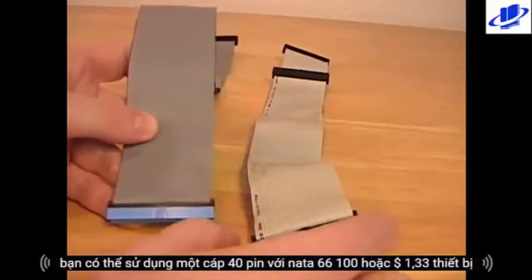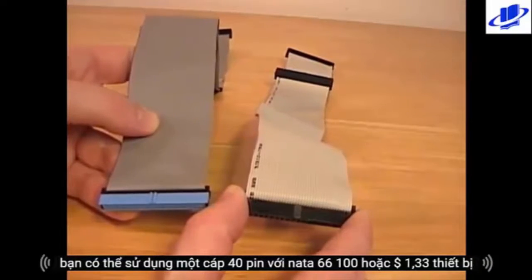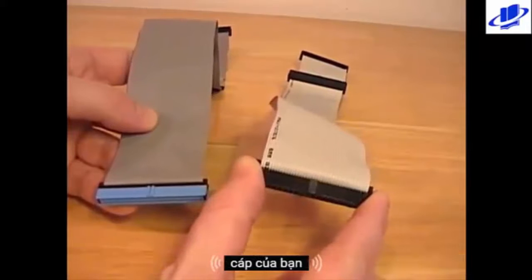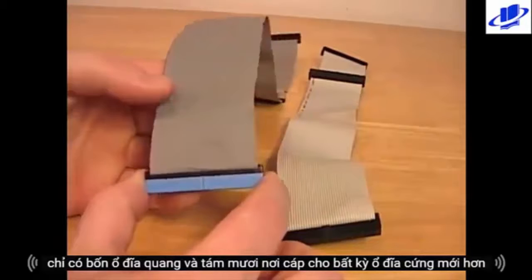You can use a 40-pin cable with an ATA 66, 100, or 133 device, but it won't run at the fastest speed. So it's recommended to use the 40-wire cables only for optical drives, and the 80-wire cable for any newer hard drives.